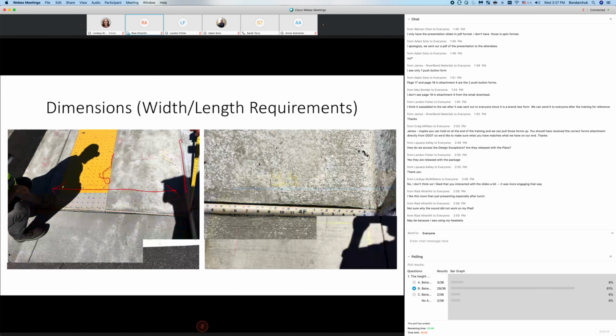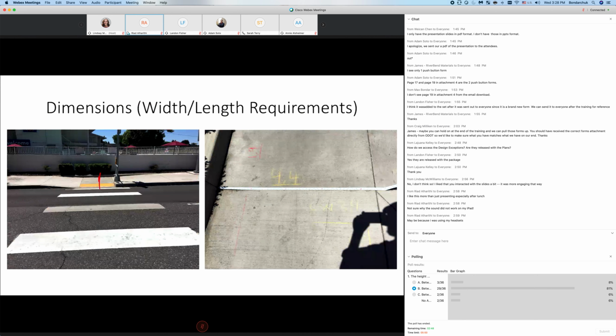Similarly here, back of ramp obstructions, 4.4 should have been 5 feet. Not sure if it's a design or construction issue, but that's a failure. We're not saying, hey, it's a contractor issue. We're just saying that these are the types of examples that fail these ramps.